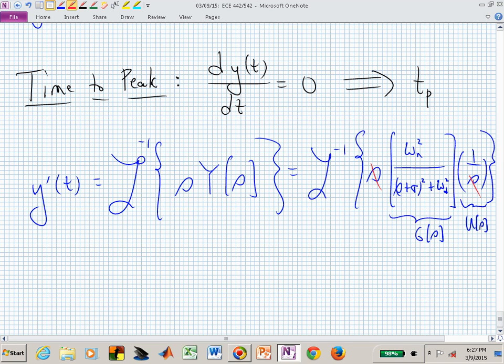It's constant, which if you go into the Laplace transform tables, corresponds to an exponentially damped cosine or an exponentially damped sine because of the complex poles and the fact that we have a sigma. That puts us into the left half s-plane, so we have an e to the minus sigma t, cosine omega sub d t or sine omega sub d t, and we could have had a combination of those if we had an s in the numerator or a linear factor in the numerator.